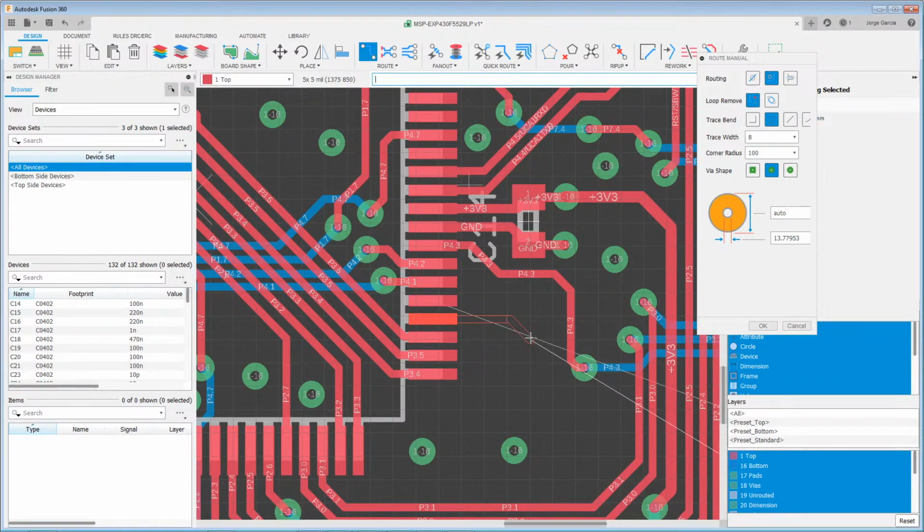The other one that I want to show you guys here is if you have this segment and you right click, you'll notice that it's going to try to switch to the complement. So when routing, I'm going to go ahead and complete this segment and move forward a little bit. Let's say I want it to end at this point. Right now I have the bend this way. So look at the end of the completed segment and look at where my mouse is now. That's point A, point B. If you right click, you get the other path to getting from point A to point B, assuming the 45-degree angle, which is what we're using. So right click allows you to get the complementary bend of the same style.